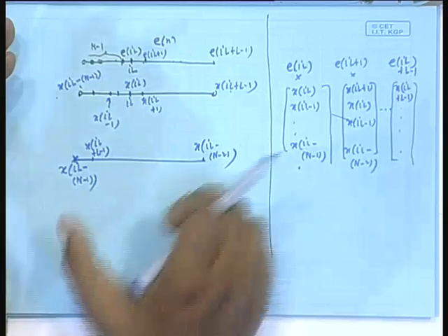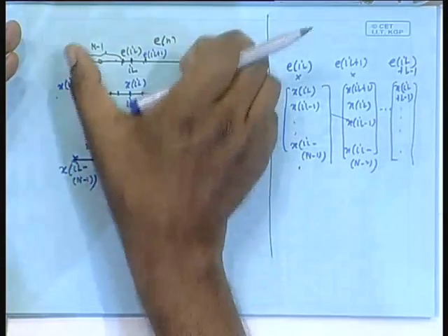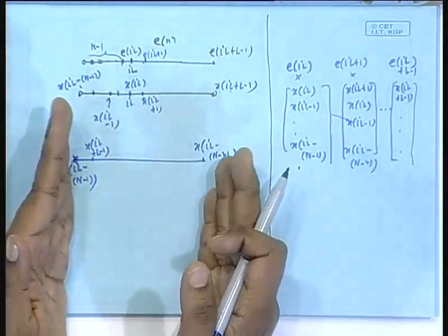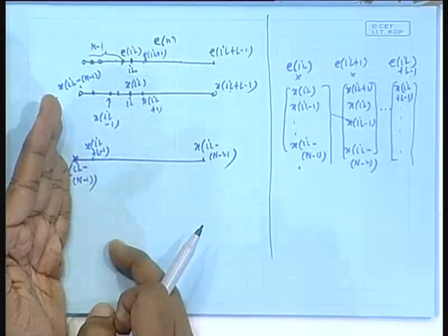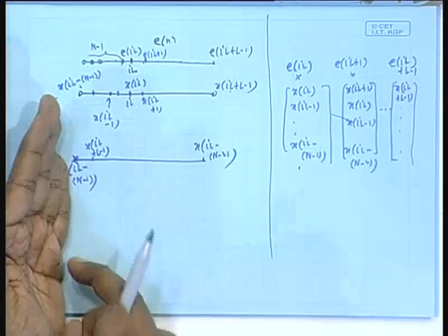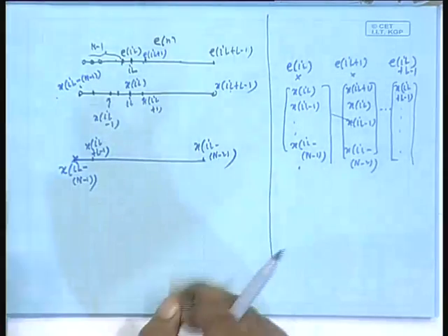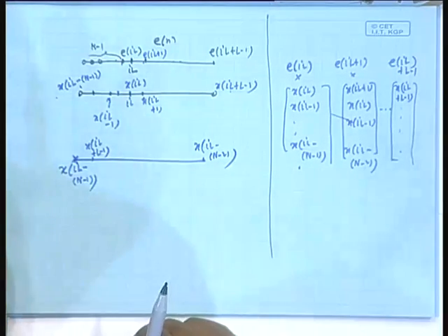Okay. Then my claim is, if you have a circular convolution between this sequence and this sequence, whatever be the output, output is over this length, but there you take only the first n, 0 to n minus 1. After that, whatever result you get, forget that. Okay. Then you will get that weight update thing.